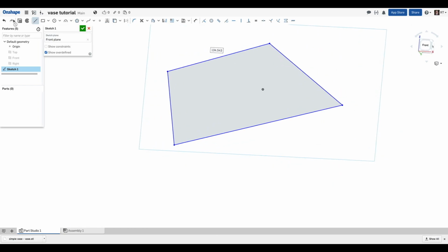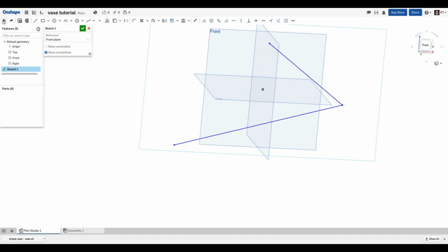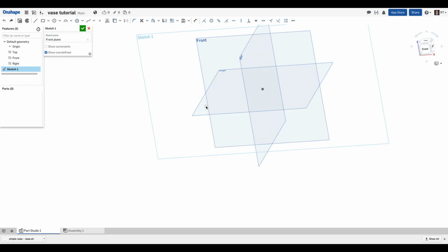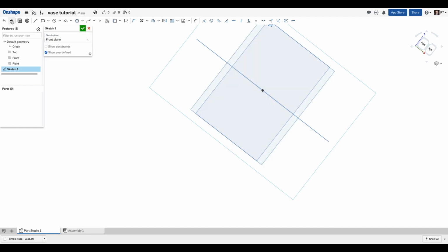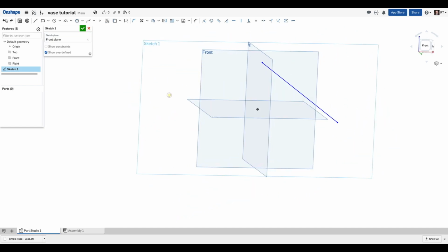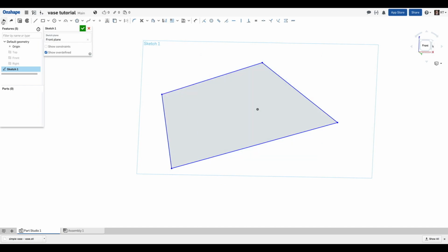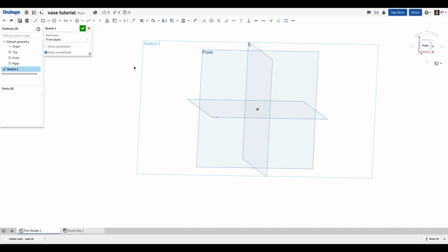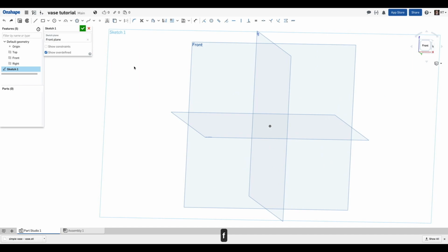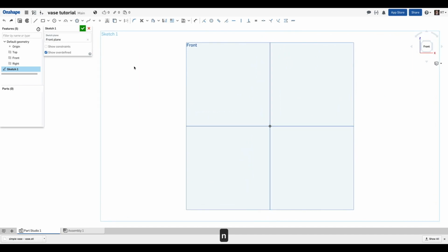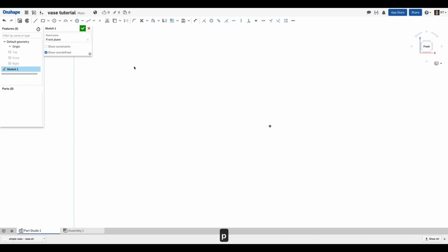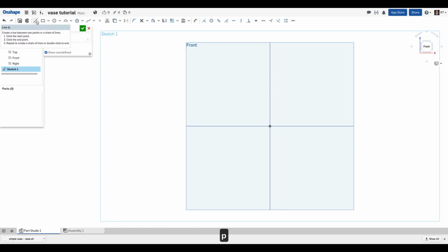Like everything else, you have the undo. We can undo, click here. It also undoes showing of things that you're working on. Doesn't undo a view angle change. Redo, undo. Again, fit, N for normal view, fit again, turn the planes off, fit, and then it'll go out to whatever your sketch is working on. Let's turn our planes on again, P for plane.